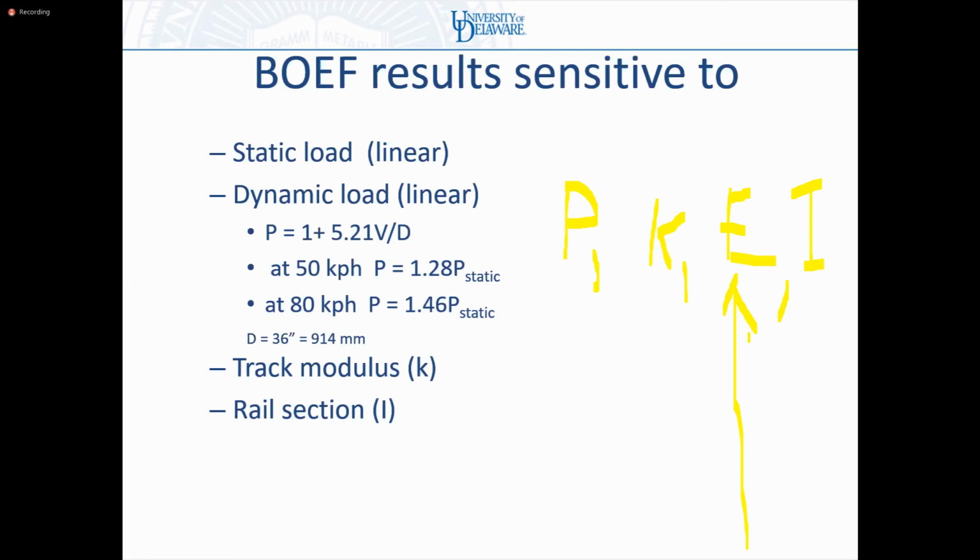For all rail steels, it's basically the same. Even between premium rail and standard rail, the E's are basically the same number. It doesn't change significantly. So E for rail steel is always the same, 207 times 10 to the cubed. The other three will vary.